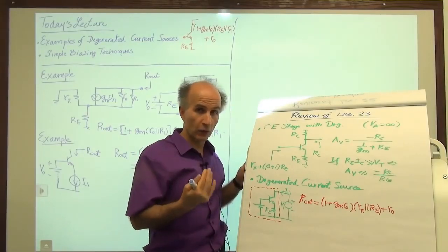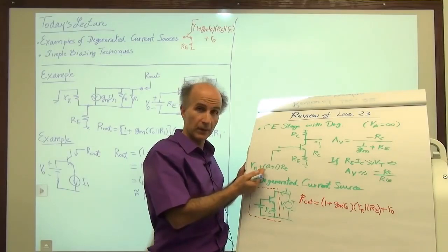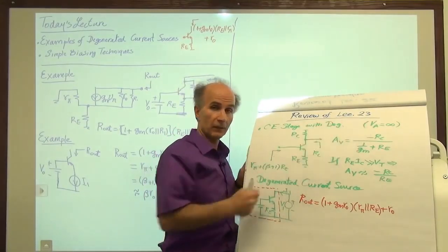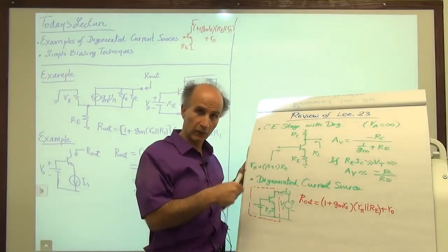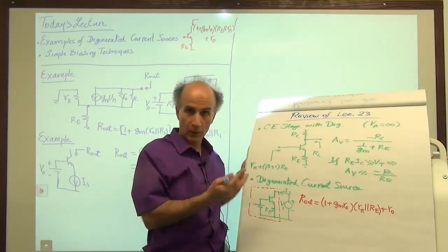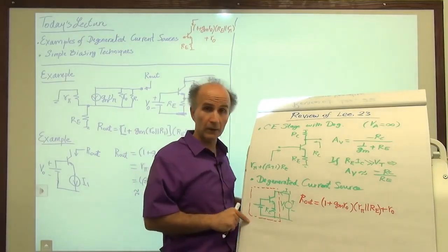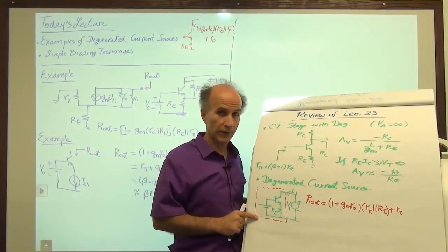In fact, I usually don't remember the equations for the voltage gain and the input impedance if the early voltage is less than infinity. I would have to either derive it quickly or go back to my notes. That's why we don't usually teach them in undergraduate courses. But it's not a big deal. You can always sit down and derive them if you're interested.